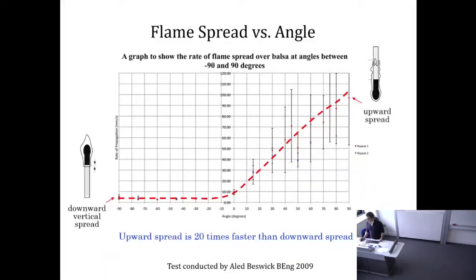We put this all together. This is inclination here, angles of inclination. This is the fuel you ignite and it's going downwards, and this is going upwards. And you can see how there is a gentle decrease of speed of burning, the spread rate. Gentle. There is always going down, but very little. Whereas in the upward, it accelerates very fast. Okay, and the fastest is if it's 90 degrees. And then if you continue going higher, it's like you swap, this is symmetric, okay? And then you can actually go all around the clock and you will get this plot.